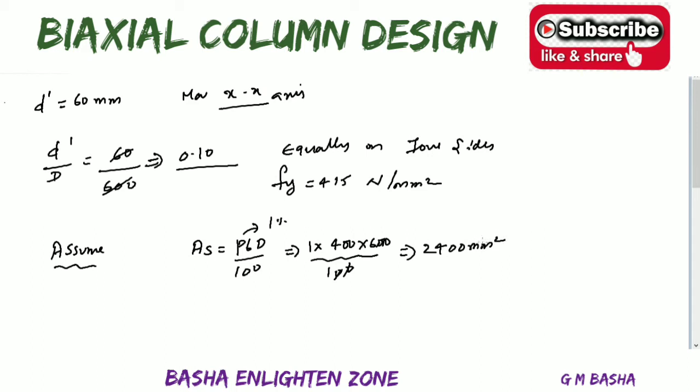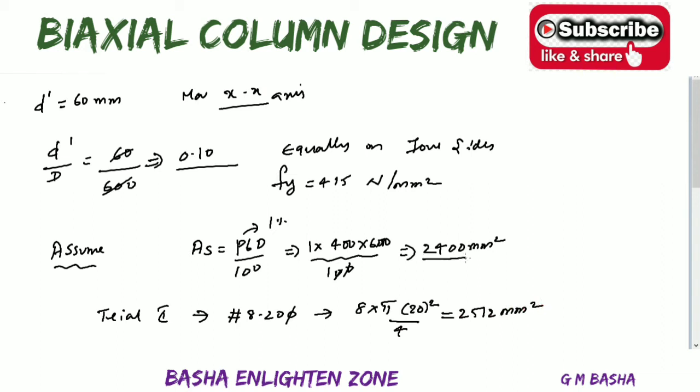So go for trial sections, like trial 1. Assume 8 bars of some 20 dia. If you simplify, you will get 8 into pi d square by 4, pi 20 square by 4, so you will get around 2512 mm square. So the required area is 2400 and the provided area is 2512.